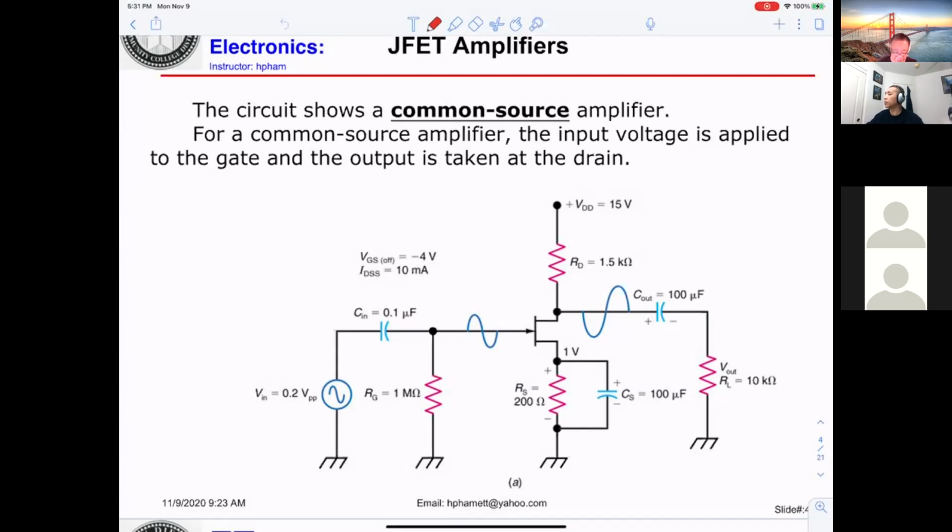One thing we already explained last time. This resistor here, you don't need it for biasing, however, it must be there. Why? Because where you apply the signal from the generator, if you're not using a resistor here, it will be shorted to the ground.